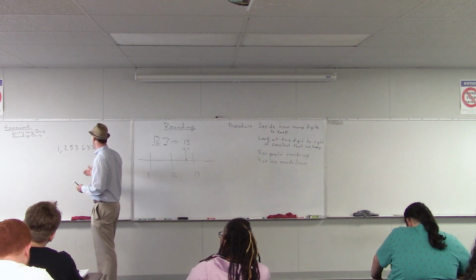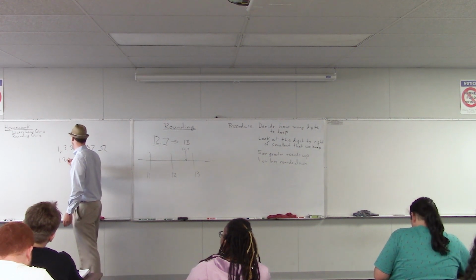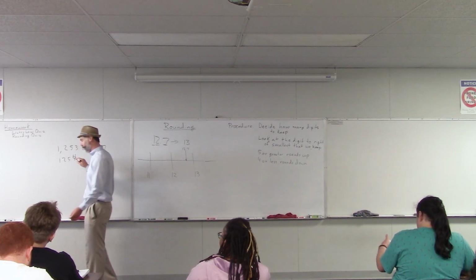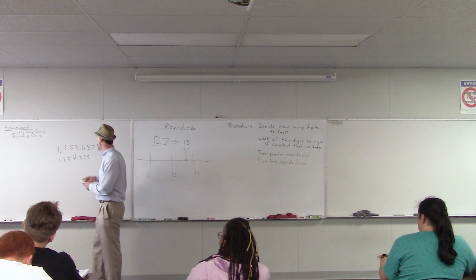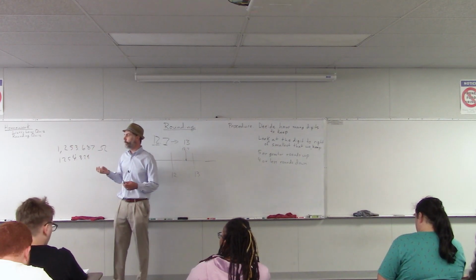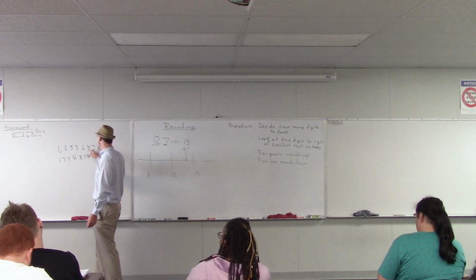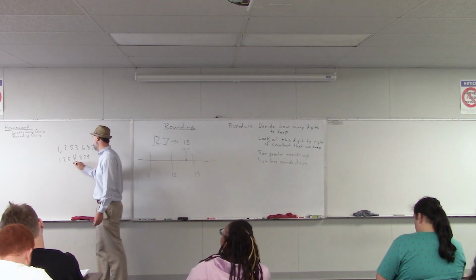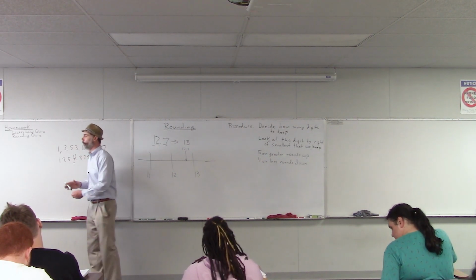But you might see that when you breathe on it and warm it up a little bit, it goes to 1,254.328 or something like that. I'm trying to write and talk at the same time. So you might see that it's fluctuating up and down by an ohm, for instance. In that case, you might say, I could write down all these digits, but it's going to change. It's accurate to about plus or minus 1 ohm. So then you might try and round your number to the nearest ohm or something like that.